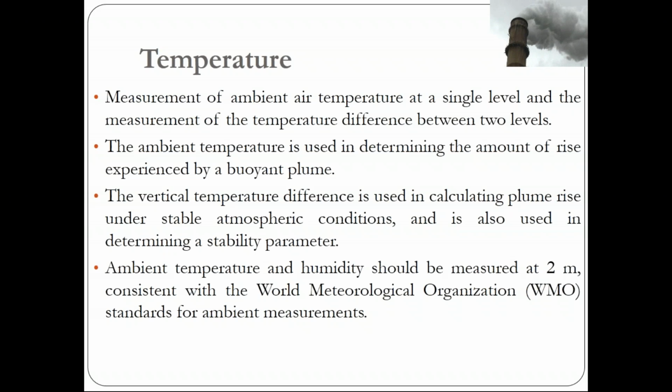They are diluting, or how they will dilute during the operation phase, when air emission will be there from the stack, and what type of pollutant will be diluted in the atmosphere. So we have to put the temperature, wind speed, wind direction, humidity, rainfall, etc., so that one can understand what type of micrometeorological conditions are there, and how much dilution may be there in the vicinity.